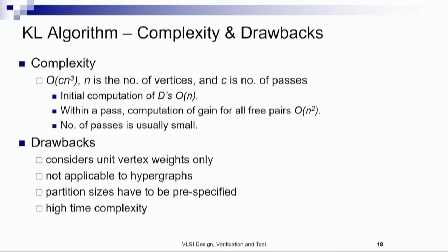Basically, we can say that hypergraphs are related to the representation of nets that can be connected to multiple blocks, more than 2 blocks. So multi-terminal nets can be represented by hypergraphs, but we will not consider hypergraphs here. Partition sizes have to be pre-specified. We can only do a bipartition of equal size, and this has high time complexity. It's big O of n cube.